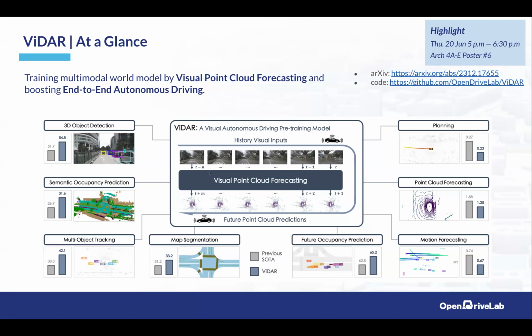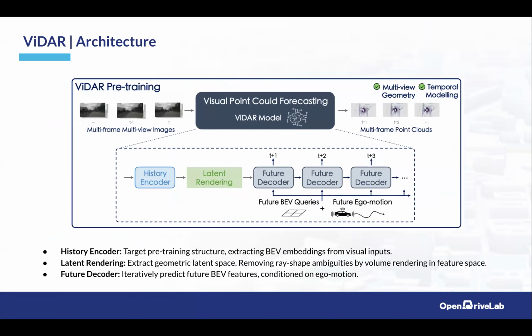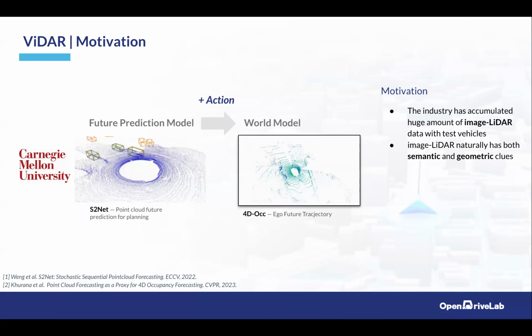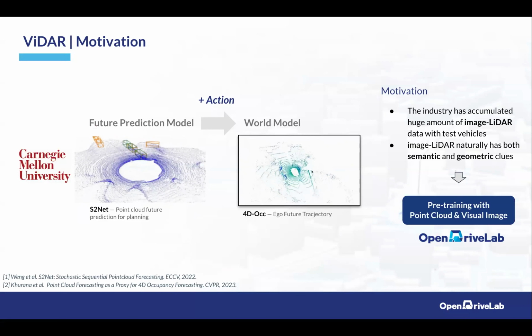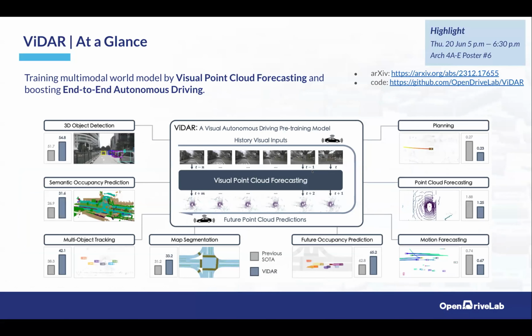Okay. So the question was how we can balance the scarcity of the dense LiDAR points. The way is that we first predict the bird's eye view features as shown here. We predict future bird's eye view features, and we convert them into 4D occupancy in this work. I didn't show it here. So we first create the occupancy, which is 3D occupancy in the temporal dimension, and we can render the LiDAR points based on the mechanism by which we think the LiDAR points should be cast.